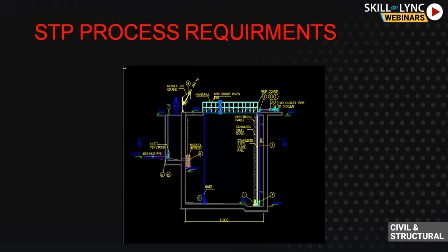There is a mixer here. What will be the weight of this mixer? How will it rotate? How do you want to fix this mixer at the top slab? Normally they are fixed at the top slab. This is small in weight. Important thing is to check there is a jib crane also on the top. Jib crane requirement should be provided from process and mechanical.